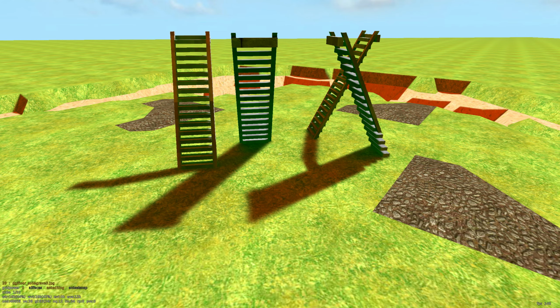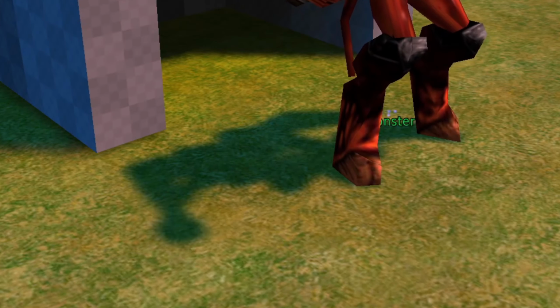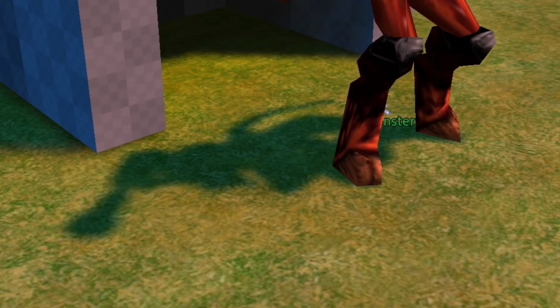What the engine actually does here is to use the falloff of shadows to multiply the sky color with the ambient color. In regions where the shadow is stronger, the ambient light has more influence, while in areas where the shadows start to fade out, the skylight becomes more prominent. For dynamic shadows, both are just equally merged with each other.